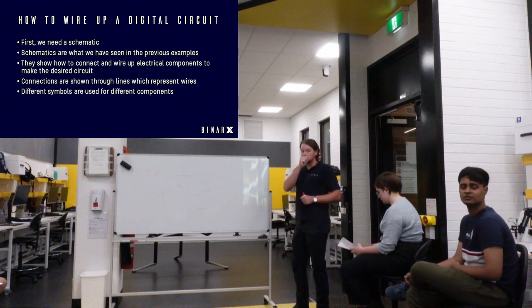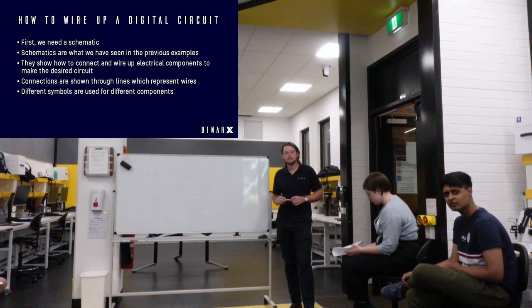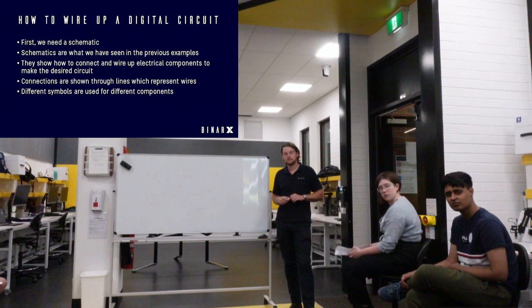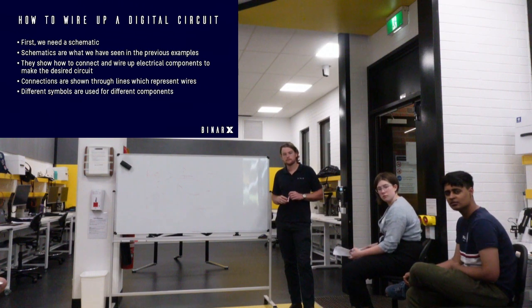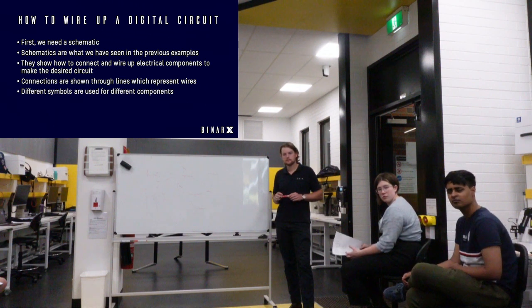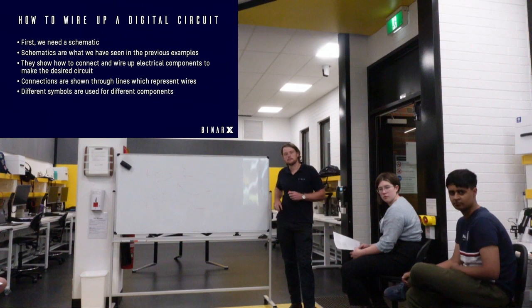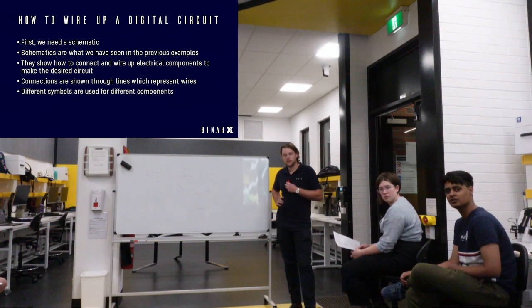One of the things you might have to do is the stuff that Fergus has just been going through, which is getting the right resistance value, especially if you're in the thermopile team, you might need a particular resistance value, but when you buy the resistors, you don't get every value under the sun. So sometimes you'll have to combine two in series to make a higher resistance.